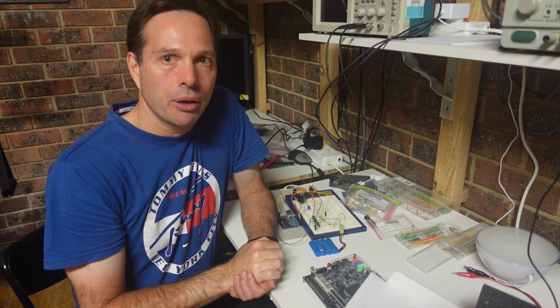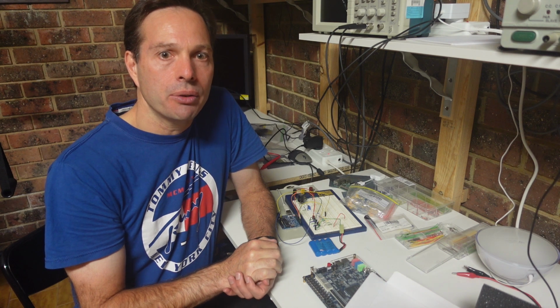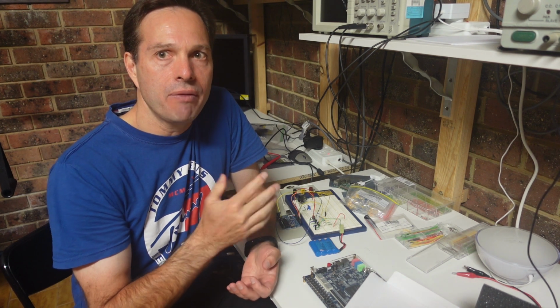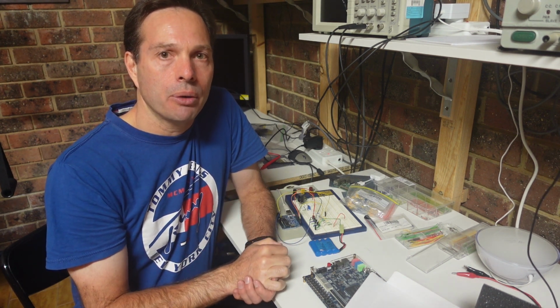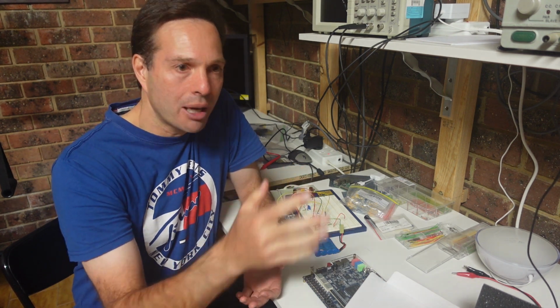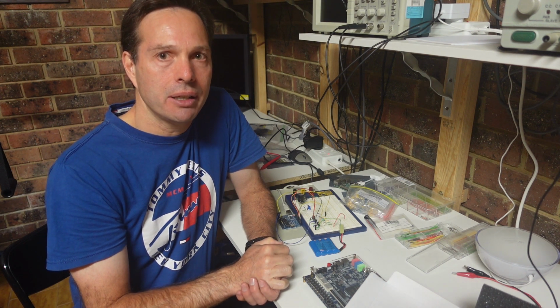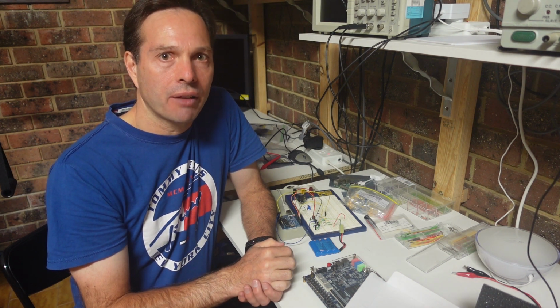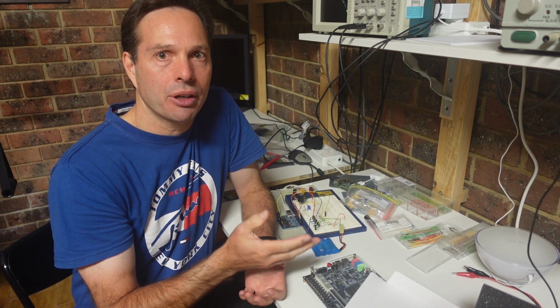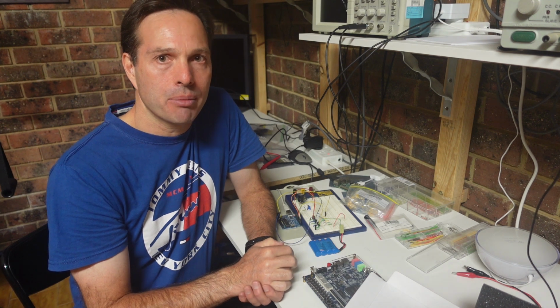With Verilog, we can do that. We can be very precise. But we can also just describe the behavior of the circuit. We can say, we want a digital circuit that does this, and we describe it using a programming language that looks a bit like the C programming language. And then Quartus has to figure out how to build a digital circuit that implements that behavior. And that can save an enormous amount of time.